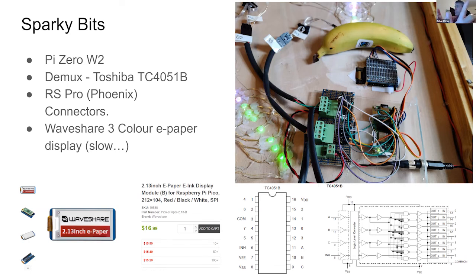So if you want repeating NeoPixels, then that's great. But if you don't, then you have to use a multiplexer to solve that. So I'm just turning on different outputs here. You're sending a 3-bit code to switch between these 8 different outputs.